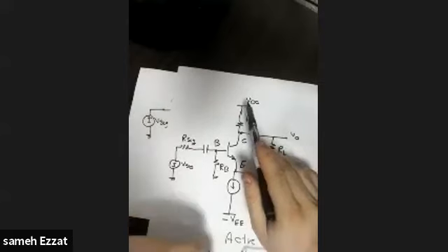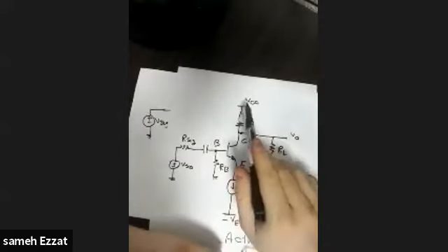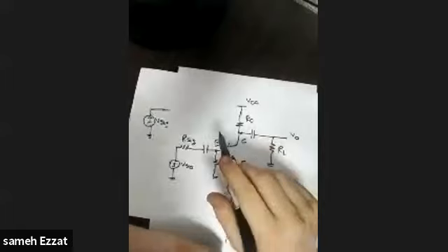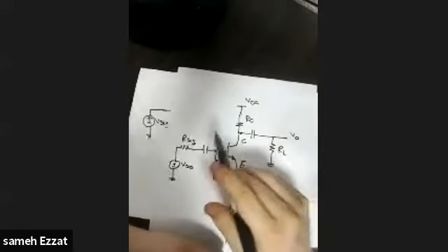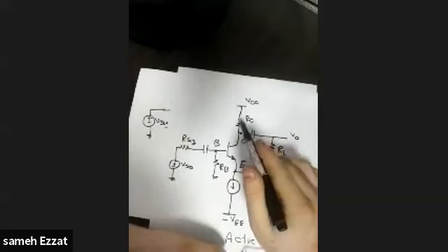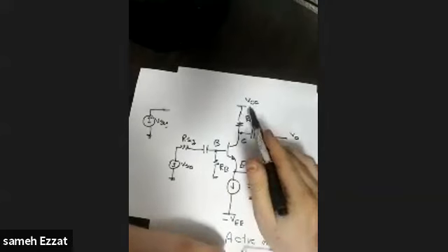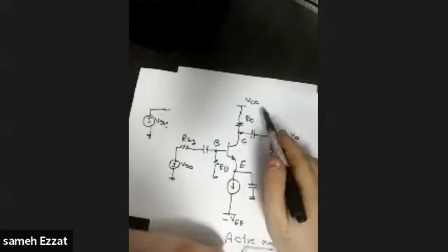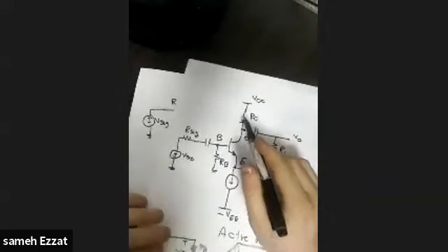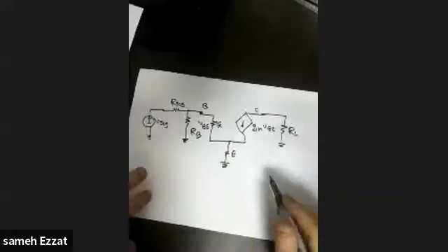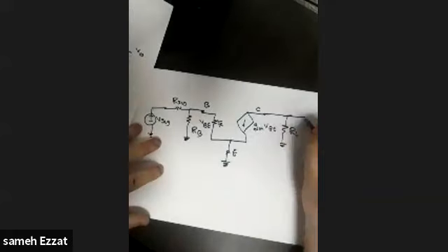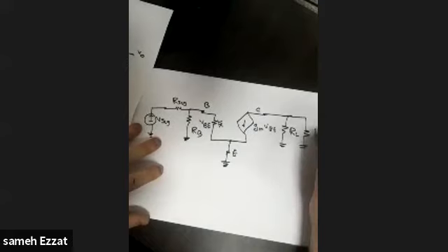But please remember that this VCC is a DC supply. Now we are doing an AC analysis, so we are deactivating all DC supplies. While you are deactivating the VCC, this will be connected to the ground. So simply RC will be connected to the ground. It is again typically what we did in the MOSFET. So we have our RC like that.